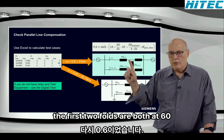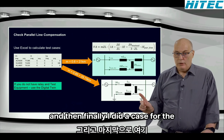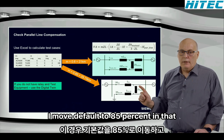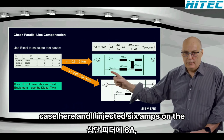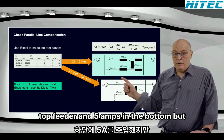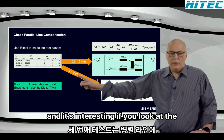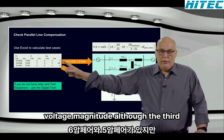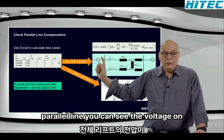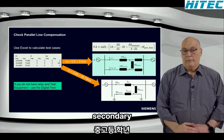So both the first two faults are both at 60%. And then finally I did a case for the bottom here. I moved the fault to 85%. In that case, I injected 6 amps on the top feeder and 5 amps in the bottom, but the 5 amps in the opposite direction. And it's interesting, if you look at the voltage magnitudes, although the third test here has 6 amps and 5 amps in the parallel line, you can see the voltage on the complete left is only 45 volts secondary for the third test.